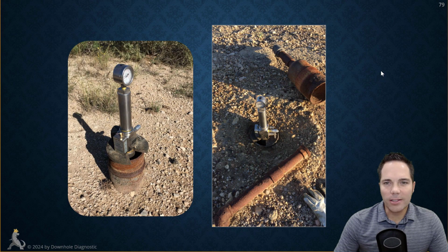So here's some really crappy wells. Let me put it this way. I was contracted, this is a while back, to take a lot of fluid level shots. These were called H15 tests in Texas, which means these are inactive wells. The regulatory body wants to verify the fluid level in these inactive wells is not above the drinkable water zone, because if there's a casing leak, they don't want you to contaminate the fresh water zone.